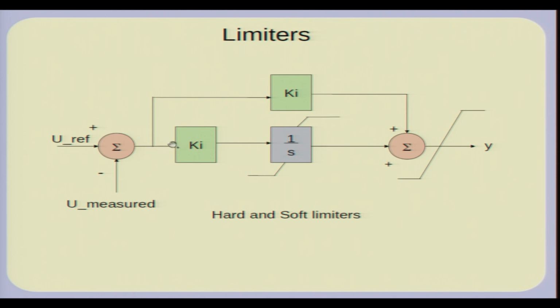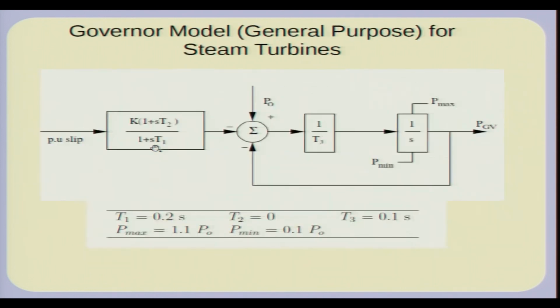Okay. On the other hand, if you have got a controller which has got an integral controller, it drives this to 0, provided of course your system is stable, and in that case the error here becomes 0. And if the error here is 0, despite that you could have an output, because the integrator is something which retains what it has done. So, you can have an output despite having this equal to 0. So, an isochronous governor would use an integral law.